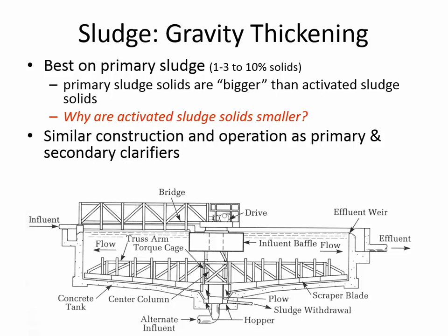Well, you know, we used it in the aeration basin as much as we could to seed that process, you know, to activate the aeration basin, but we have to dispose of some of it. You know, we can't keep recycling all of it or else it'll accumulate in the treatment plant. So we have to have some of it that we're drawing off and disposing of. So, you know, we can reuse it for fertilizer or we can incorporate it into bricks. That's one thing that they do is they mix the sludge along with clay and water to make bricks, but we don't have too many options for what to do with it.